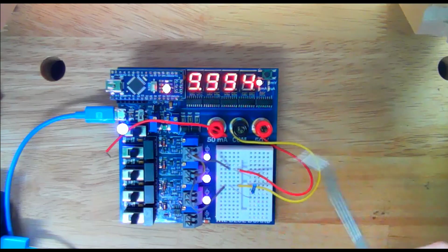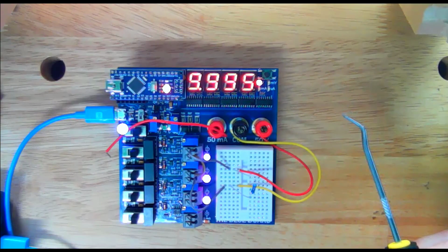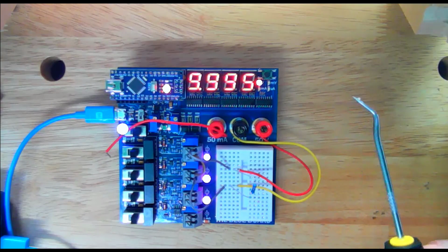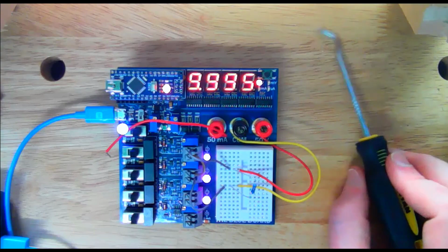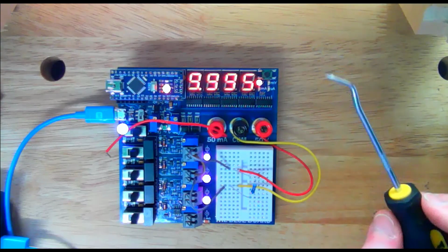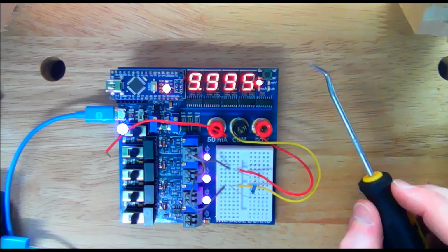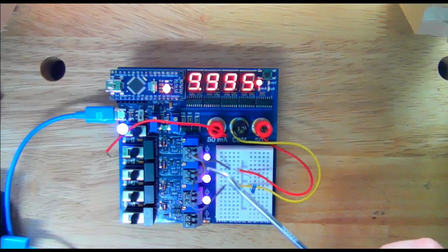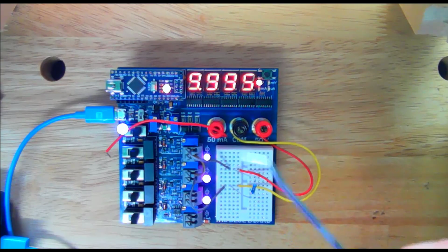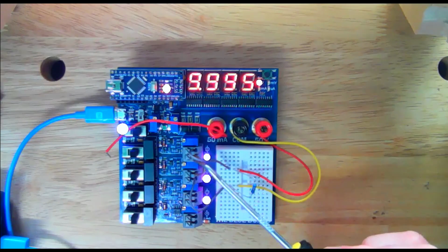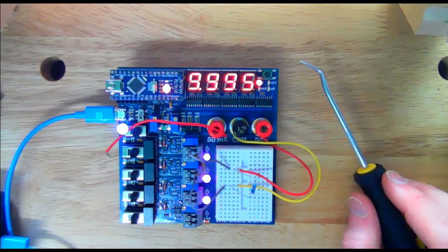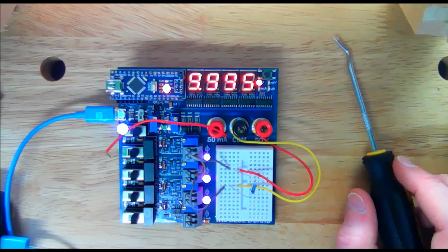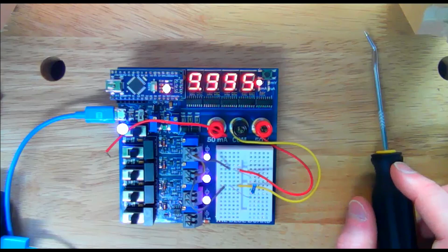So by connecting these supplies in series, we were able to get 10 volts by combining the 7 and the 3. But the cool thing here is these are isolated supplies, so we can connect them in any orientation we want. So let's make a 4-volt supply by taking the 7-volt supply and connecting the positive terminal of the 7-volt supply to the positive terminal of the 3-volt supply, and then connecting the negative terminal of the 3-volt supply to the top of our resistor. So essentially we have a 7-volt supply oriented right side up and a 3-volt supply oriented upside down.